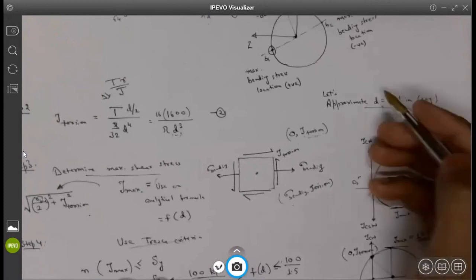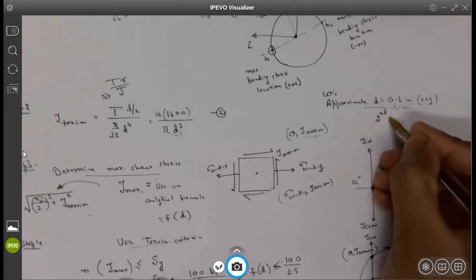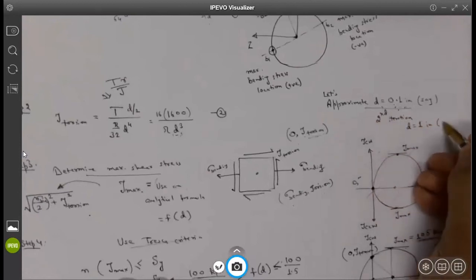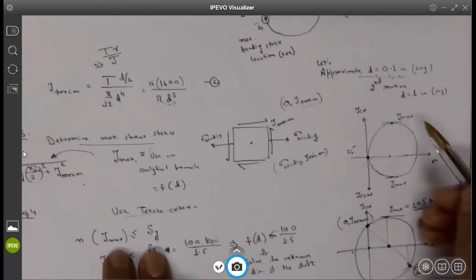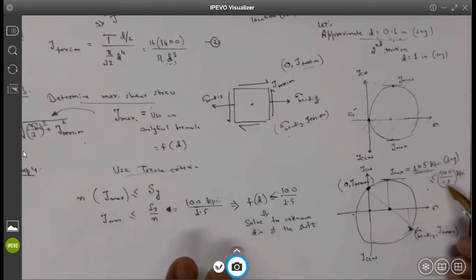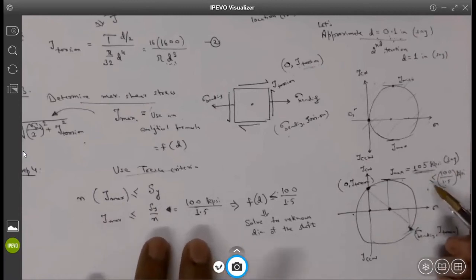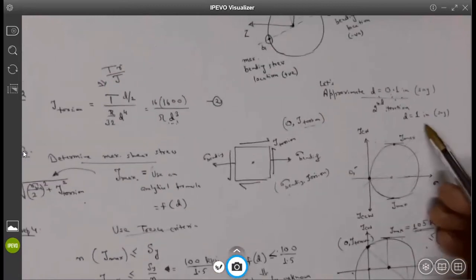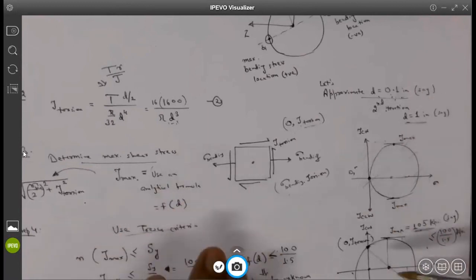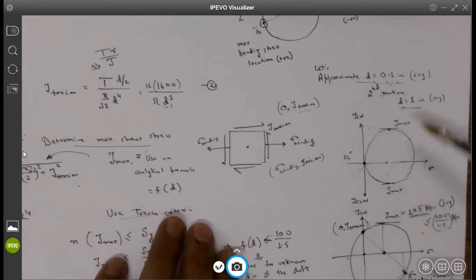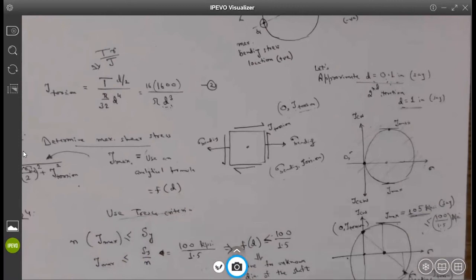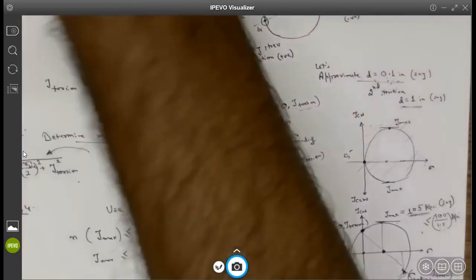So when you make it 10 times, our next iteration, second iteration of your calculation, say D is 10 times of this original first iteration, and then you do all this calculation and you find tau some value, and you see whether it is less than or bigger than that. So if you find that it is much less than this, that means I need not go for 1 inch diameter, but I can go even smaller. So that is what we do, the iterations. The calculations are happening in iterations to see when you satisfy the criteria for failure. Does it make sense?